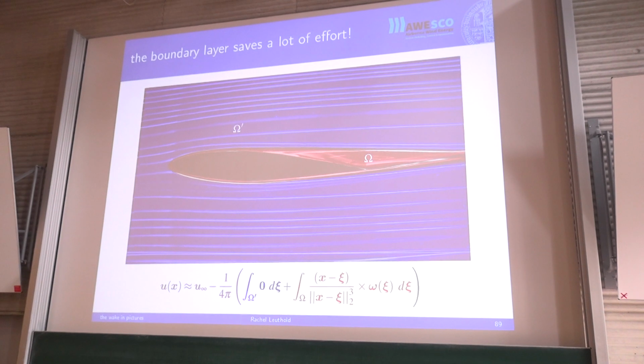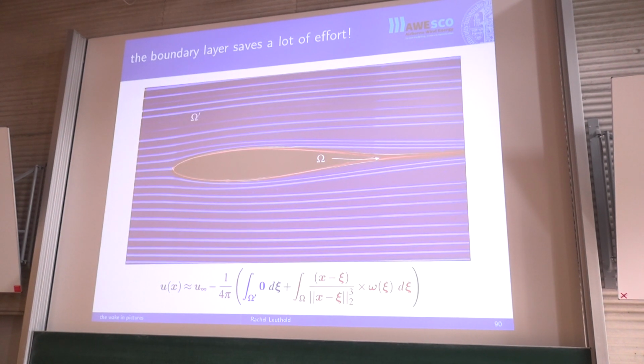There's also one particular circumstance in which the problem becomes even nicer, and this is why people are frequently so happy when they say fully attached flow. At this point, the boundary layer is thin until the trailing edge, and then remains thin more or less after the wing as well. So effectively we've dropped one dimension from our integral. If in this photo we have a surface as our domain, then the new domain of our simplified integral is really only a curve. Clearly this is a big savings in the effort it takes to integrate this thing.